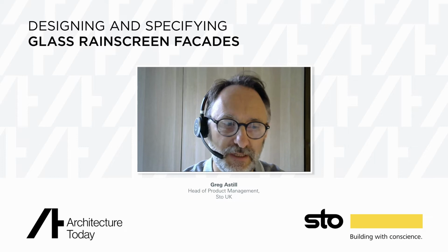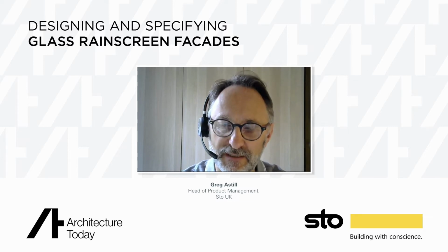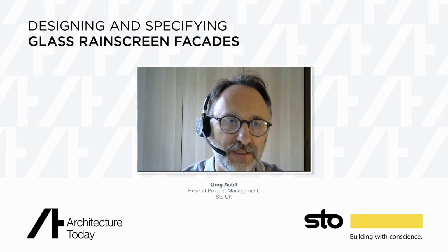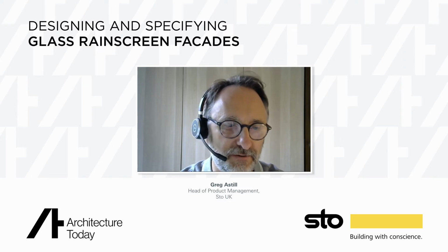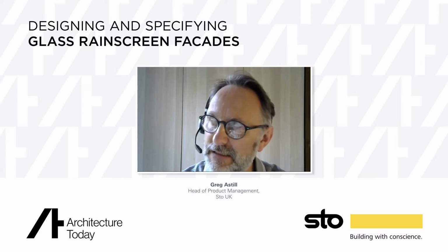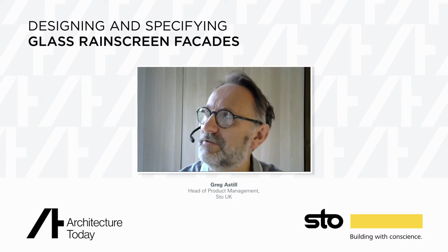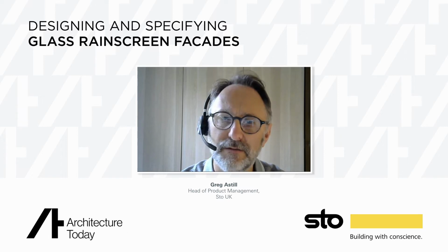Way back when we first started with glass in the 90s, that wasn't a standard process. It was something that had to be requested, but we've since learnt from that, and every single panel that goes through now is heat soak tested. And I think, from memory, might be wrong here, it reduces the chance of something like that happening to about 1 in 40,000.